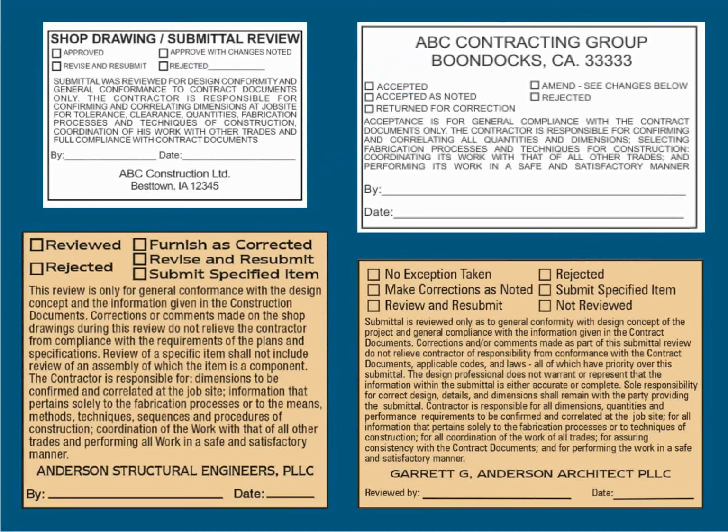I would just say one last thing about these submittals: when they come to you, be timely with them. They become the center of litigation more often than any of us would like to imagine because we don't handle them on a timely basis. And they are an important tool for the contractor to stay on schedule. While the submittals themselves may not lay a lot of responsibility on us, the return of that information is critical. So in the specifications, when it says you'll return them within 5 days, be sure and do that,